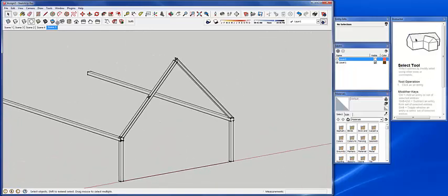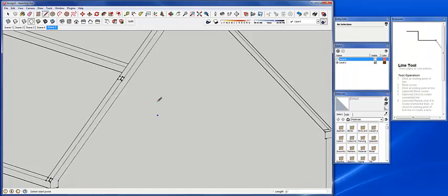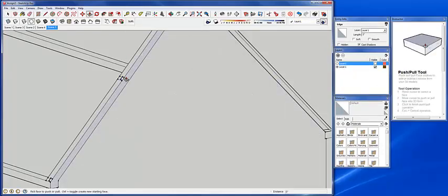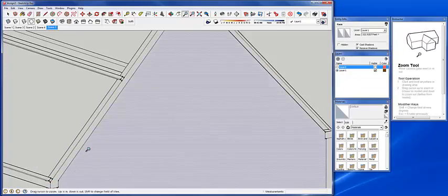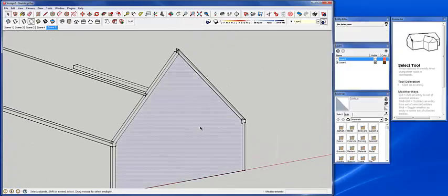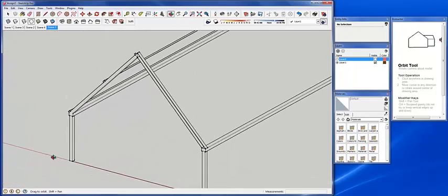And so there's a couple things that have happened here. If we look at this, let's Z to zoom in. We can actually see on the interior edge of this, if we use the line tool, as long as we have a closed loop, we can just redraw one of those lines and it'll rebuild that edge. And we'll, again, use the push and pull. 40 feet. 40 feet. Delete that as well. Alright, and you guys are starting to get a sense of how this is going to work here.